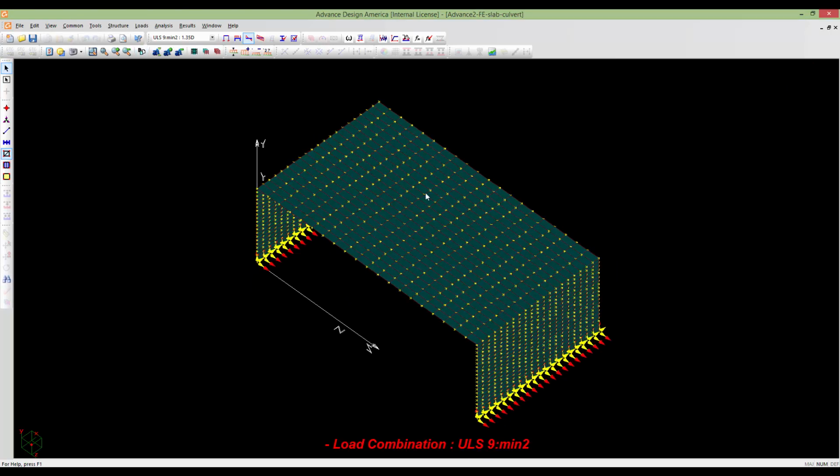To check for the design, you just need to click on your placement window, and here you have all of the orientations. You can have them all or check one by one. For example, if you want to check the reinforcement for slab, just click it here, and you can use these icons here to view the rebars in any direction, in top layers or bottom layers or both of them.